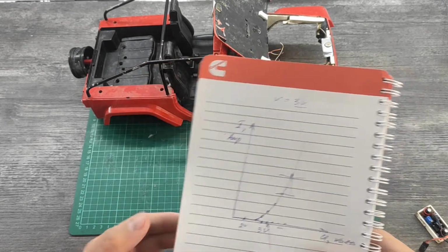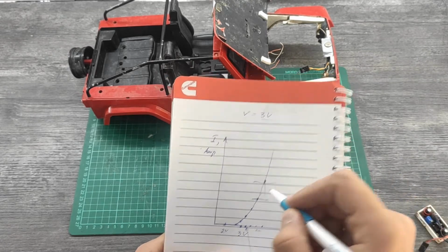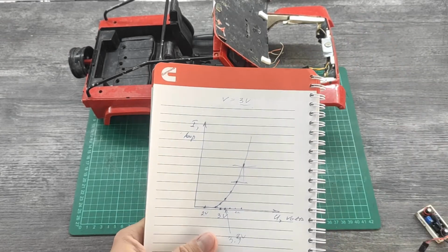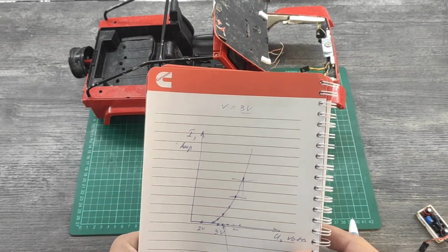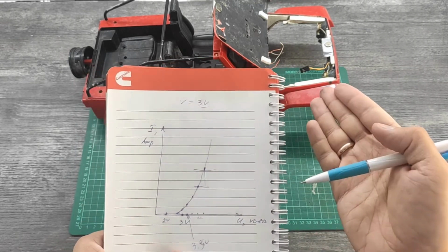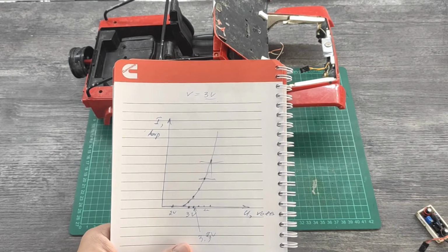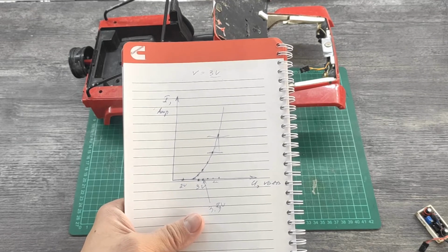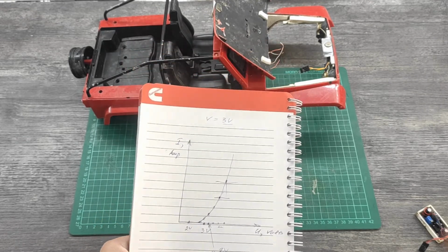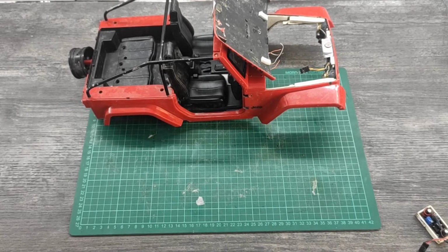And what we need to do is limit this current, so our diode will live a long life. If we were using common 5mm LEDs with 10 or 20 milliamps, it's easy, you just use a resistor to limit the current, and that's it. For high power applications like this, you need to do something different. Okay, what are our options?